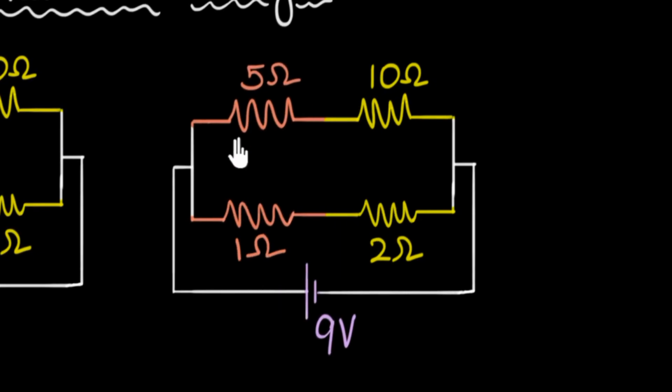First, I would like to make a copy of this circuit without that red resistor and see how the voltages get distributed everywhere. That will give us the clue. All right. So in this particular case, current is running and everything. Over here, notice now these two resistors are in series. Similarly, these two resistors are also in series. And you know, in series, current is exactly the same.